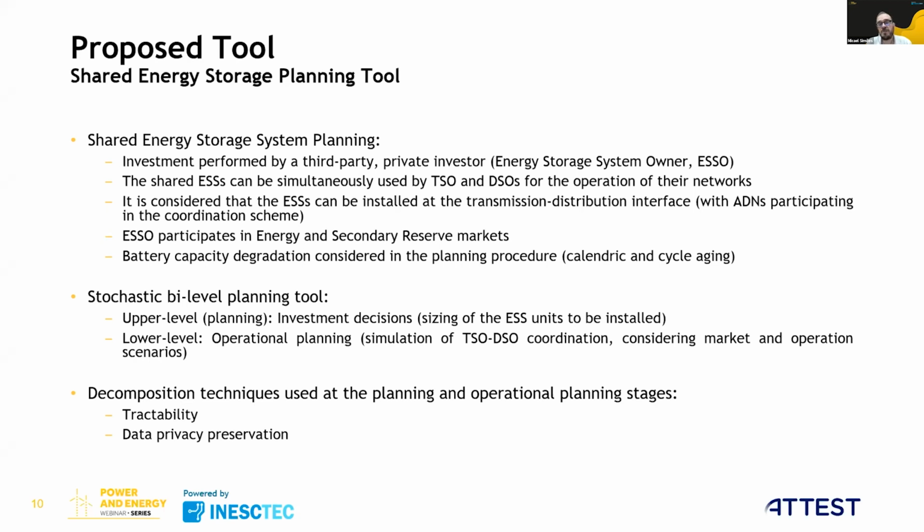The investment is performed by a third party, what we call the energy storage system owner, and the shared energy storages can be used, or simultaneously used, by TSO and DSO for the operation of their networks. Furthermore, it is considered that the ESSO can participate in energy and secondary reserve markets, and a battery capacity degradation model is considered in the planning procedure.